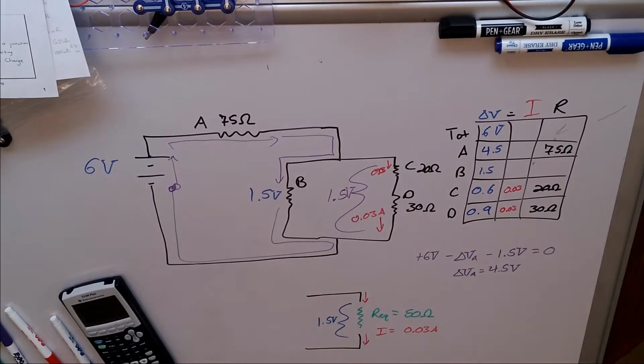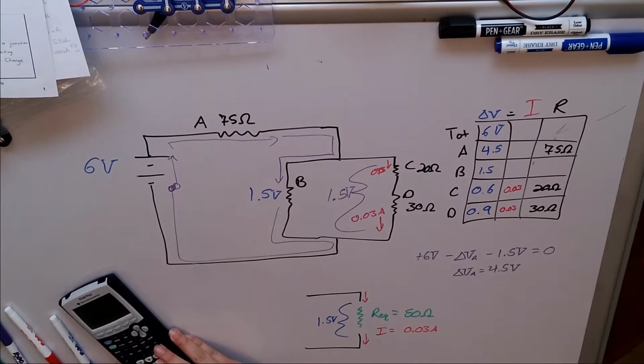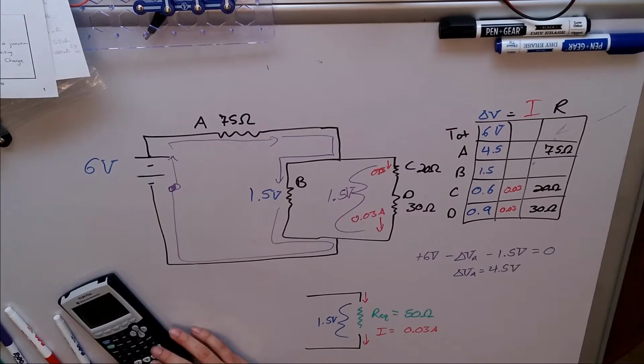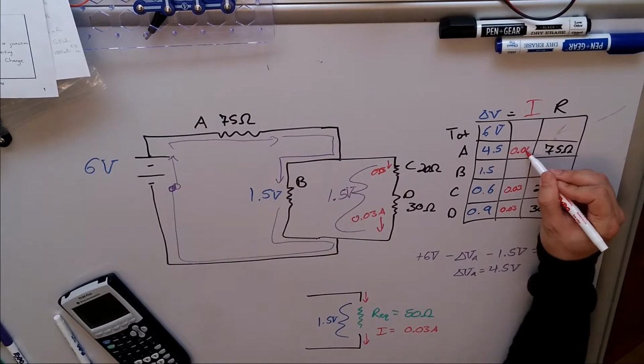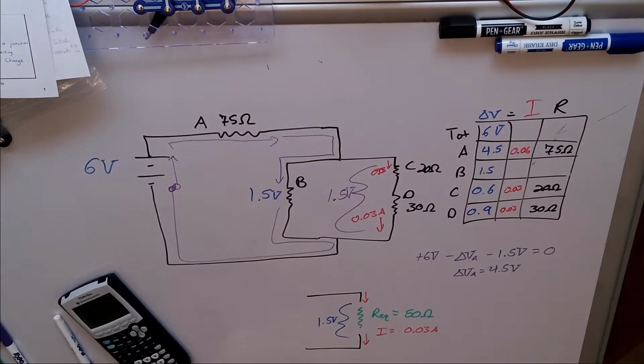Let's pretend that we didn't do that initially, and let's go through. We now know that we've got 4.5 volts here, so 4.5 volts divided by, well, actually, I think we did need to do that in order to solve this completely. I gotta be careful with how I set this up. 0.06 amps is our total current. Now, with the stuff that I did here, I apologize. I think I did not give enough information on B for you to solve it any other way than doing this advanced approach. But this is good because a lot of times on the AP exam, they'll give you part of a circuit that you have to do an analysis on. So this is a good heads up on some of the advanced stuff that you'll need to do.